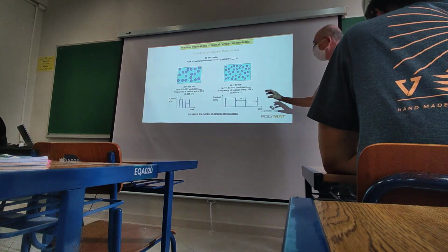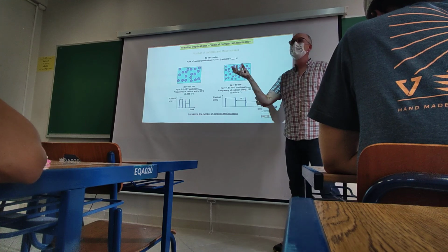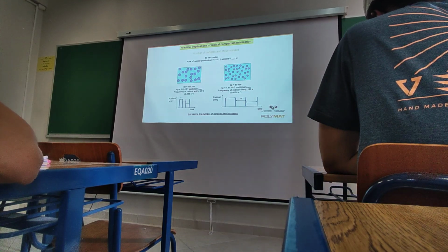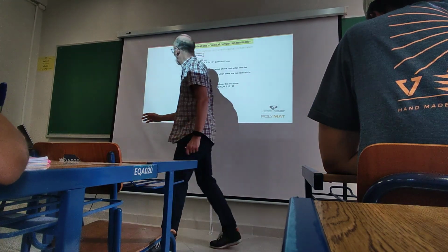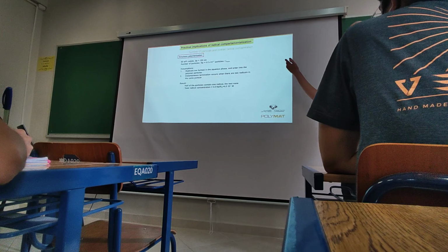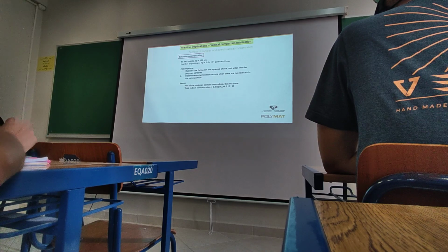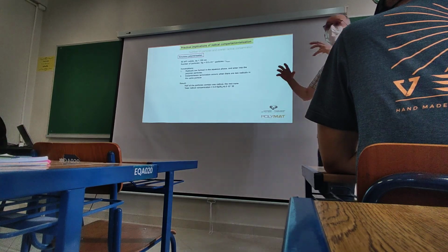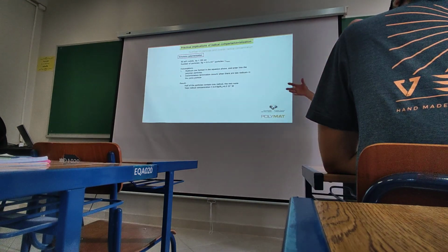So you don't have particles in a homogeneous system, so you don't have the possibility to modify the number of particles, whereas in emulsion polymerization, yes. Okay? So this is one of the implications. The second one is the one that we mentioned before: because of this reduced termination, the radical concentration is overall much higher in emulsion polymerization than in a homogeneous system.